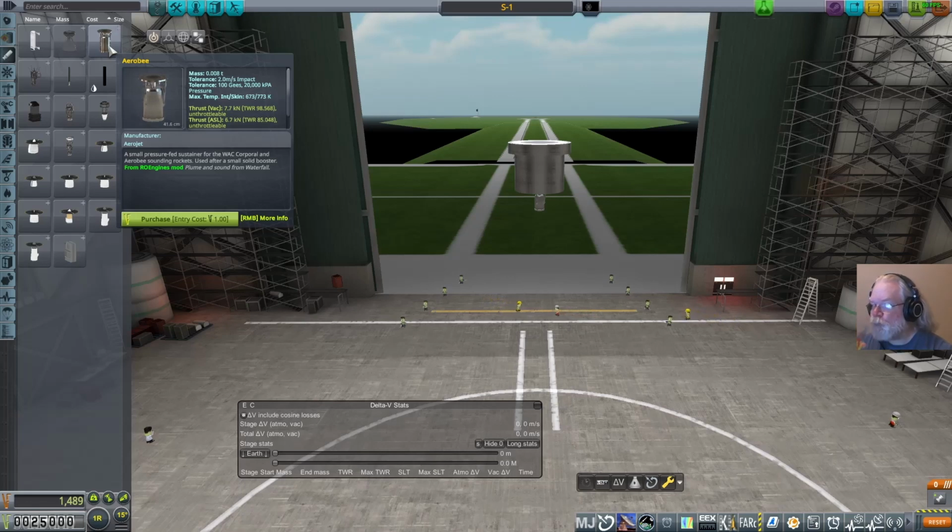This engine has some properties that are interesting. For example, if there's a bubble in the fuel tank, and there will be when you start burning fuel, the end of the fuel tank near the arrow B can't have the bubble in it, or the engine will stop. So you either ignite this on the ground, or you ignite it in the air, but something else is pushing the rocket forward, so you get some acceleration.